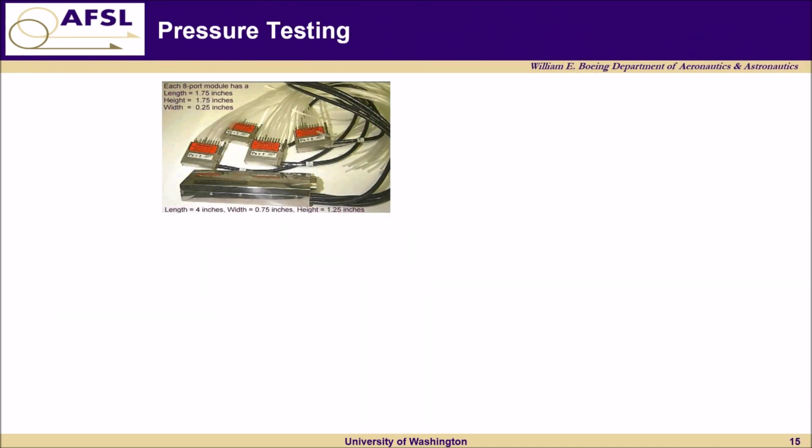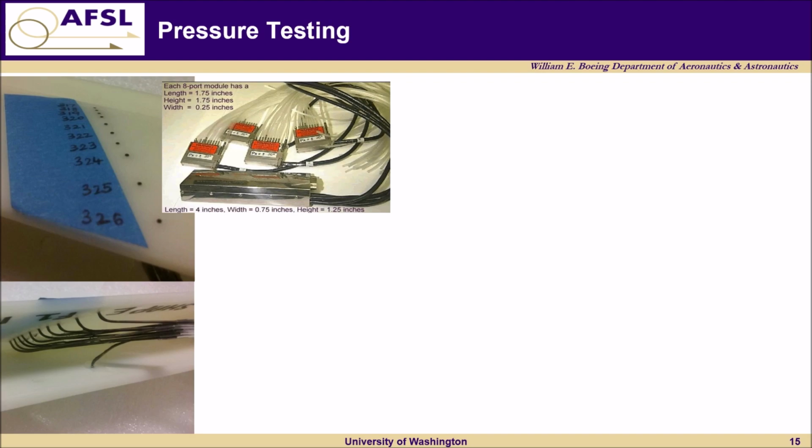Continuing with our topic of non-standard data that you can acquire in a wind tunnel test, a very popular option is acquiring pressure data on a model. So this involves using an electronic pressure scanning system, or EPS, to measure the static or total pressure at various locations on the model. Now, often this means installing lots of little pressure ports all over the model, and this can be a pain to install and wire all these ports.